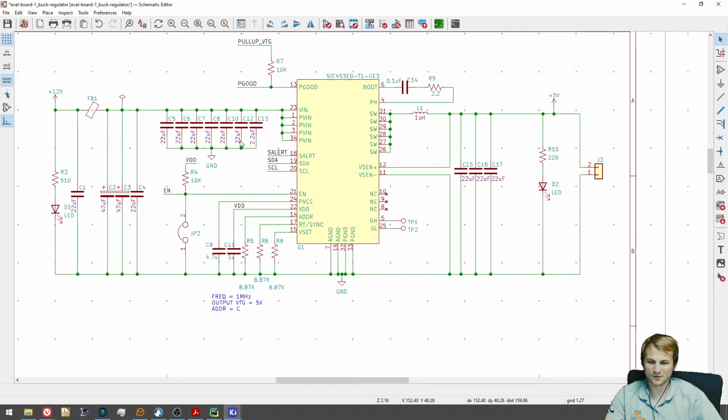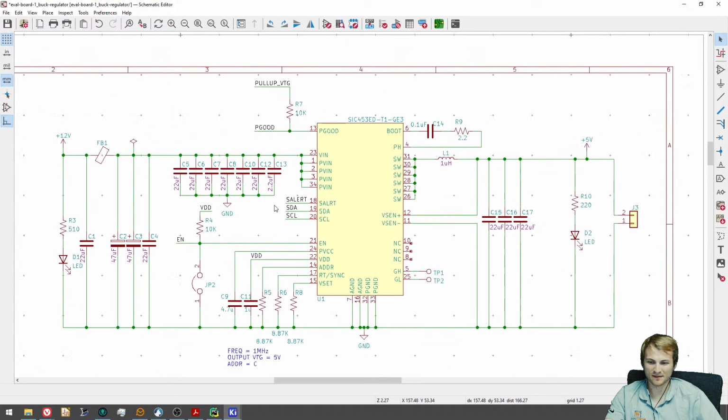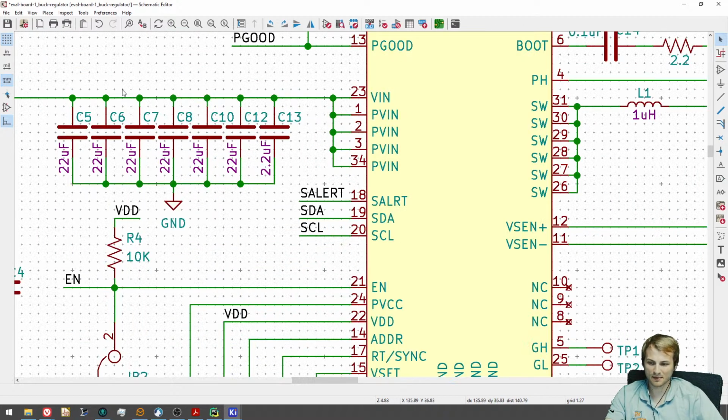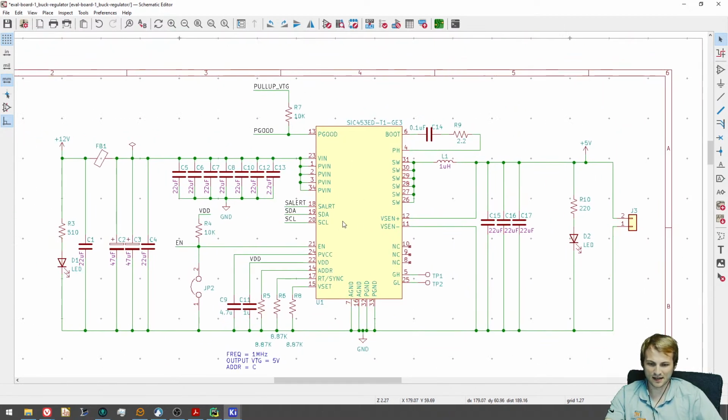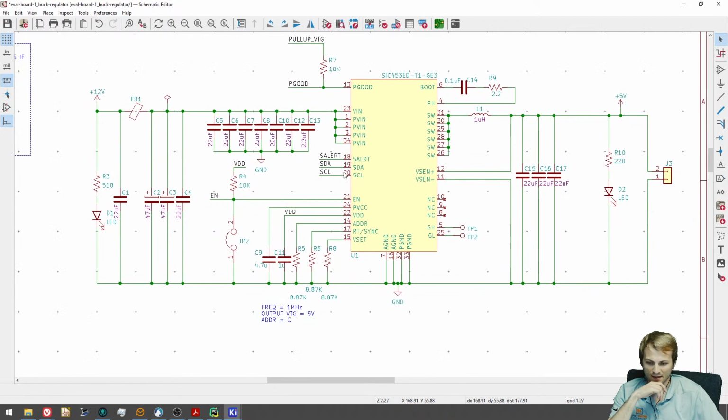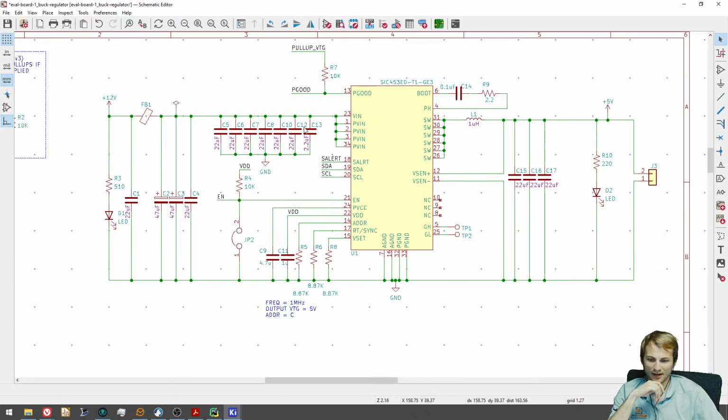So what people will do, and this is what Atmel and them will say, is, oh, just put a bunch of capacitors. That's how you get the high speed switching. That used to work maybe 10, 15 years ago with slower ICs. You can't do it now because anything over 500 megahertz, capacitors, even ceramics, are useless.